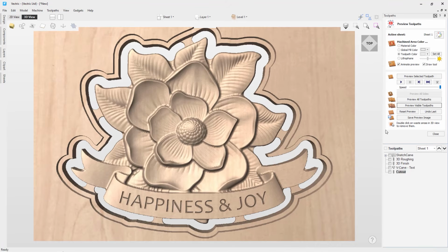So the last step I want to do is just a little bit of organization down here before we save off our toolpaths. So I want to put these into a group. So we're going to do what we did before. We're going to right click, create an empty group, then right click on that group and choose rename 3D carving. And we can just drag these up into that group. Again, that way we can keep both options available to our customer in the end. I don't need to rework all this. There we have it, and that looks great.